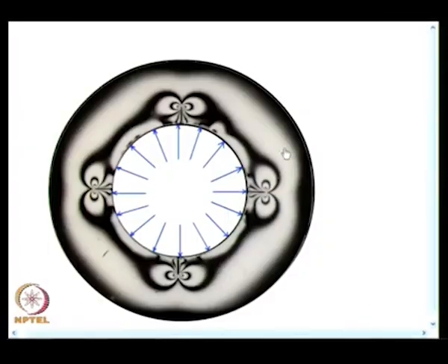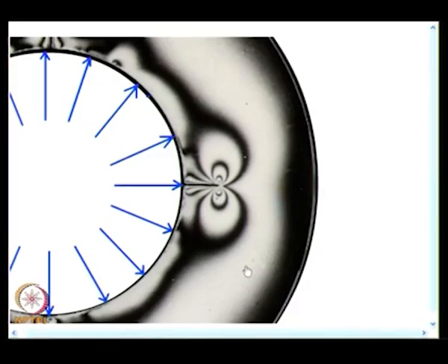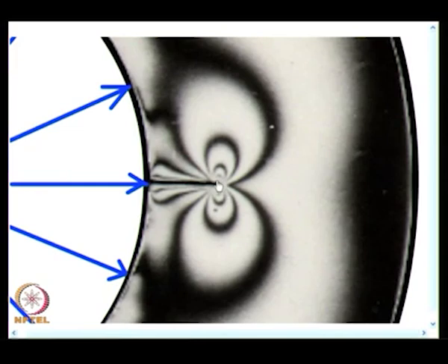Now, what I will do is I will magnify this further, and I want you to observe a few more things. I think it is reasonably big enough. Let me see one more. And can you see here I have this as a crack. In the earlier examples we saw the fringes were tilted forward. Here the fringes are tilted backwards. You have a very complicated combination here. The first fringe is backward tilted, the second fringe is also backward tilted, the third fringe is forward tilted, and the inner fringe is almost straight. If your eye is tuned, you will be able to see this.